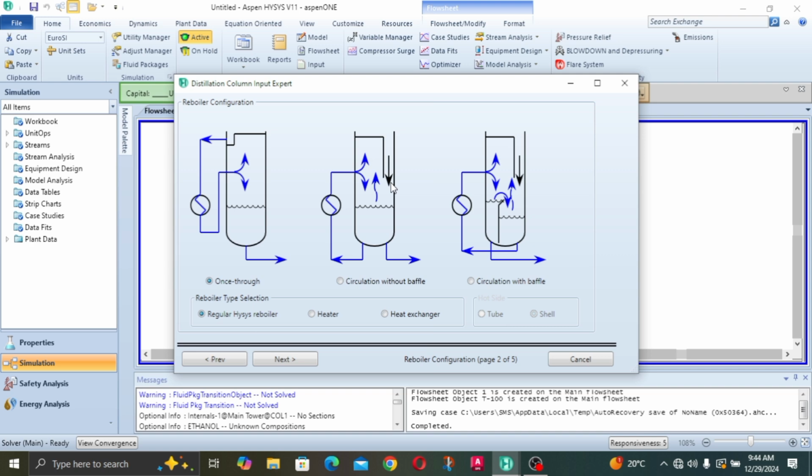It's more like the weir in our separator, the weir that separates the heavy liquid boundary and the light liquid boundary inside our horizontal 3-phase separator to avoid them from mixing. But in this case, the baffle is the nudge inside that does a little primary separation before the main distillation separation technique takes place for our mixture.